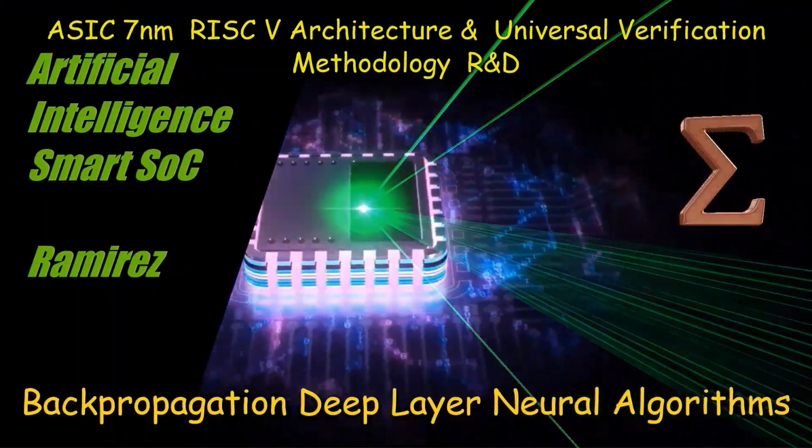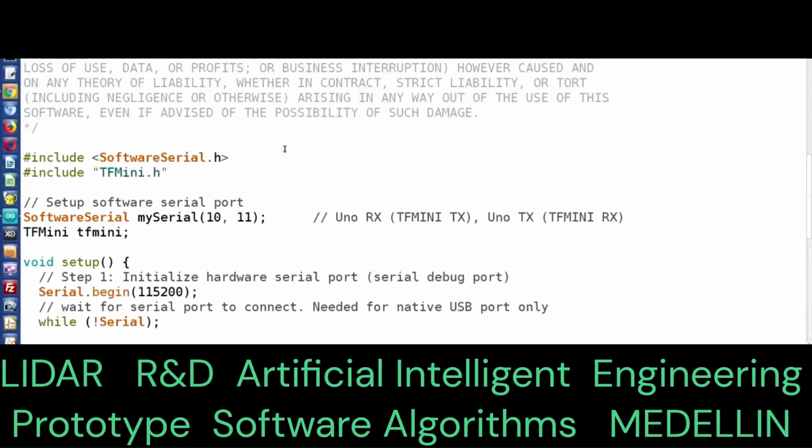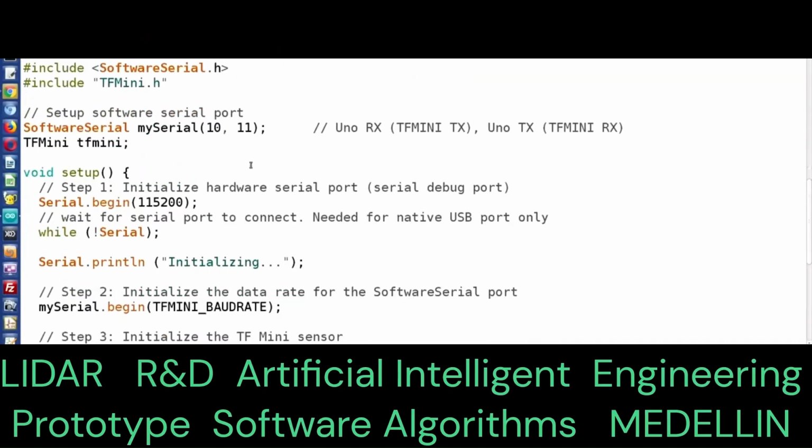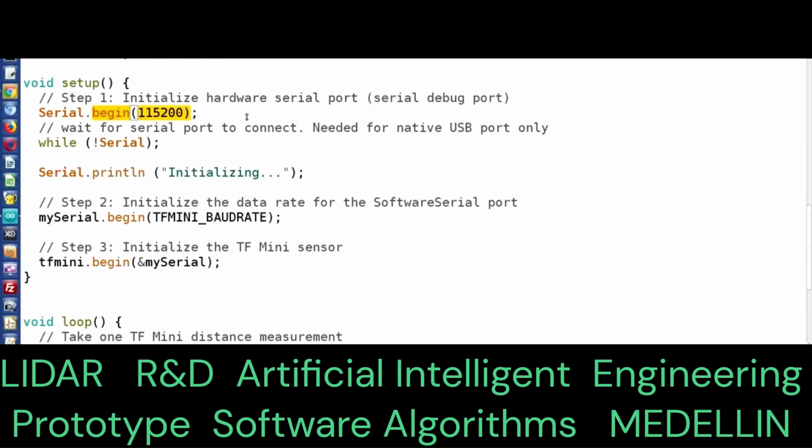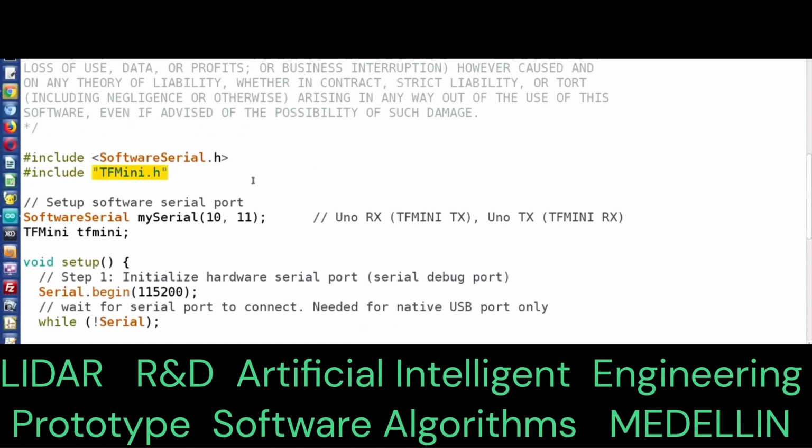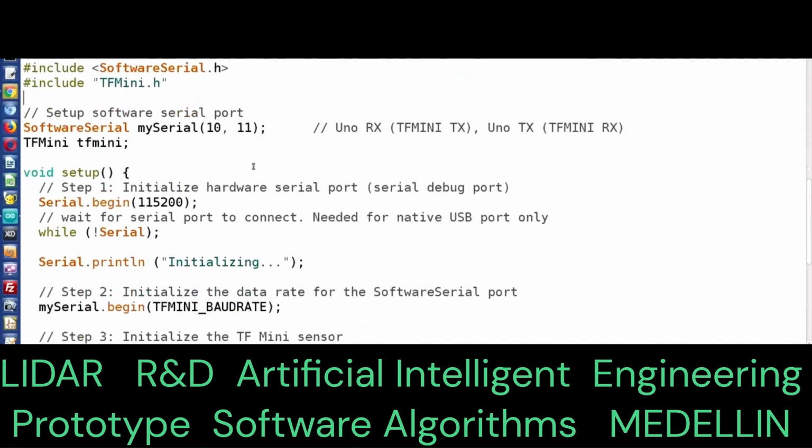So, first include the SoftwareSerial.h file. Then include the TFmini.h file. Now let's set up the software serial ports.